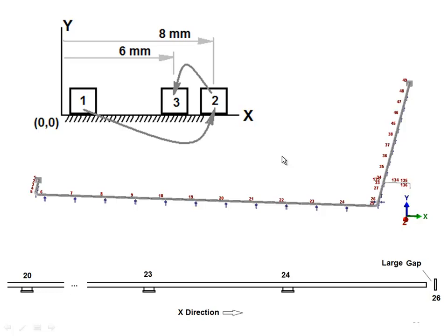The total displacement at node 20 is still in the plus X direction though. This is shown in the diagram at the top of the slide. The block in the figure slides to position 2, stops, and then reverses direction and slides to position 3. When the block shifts direction at position 2 and begins sliding again, the direction of the friction load on the restraint switches also. For programs that base the direction of the friction force on the total displacement of the restraint, for cases like this as shown in the top figure, the loads will act in the wrong direction.